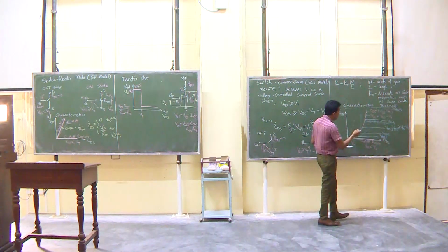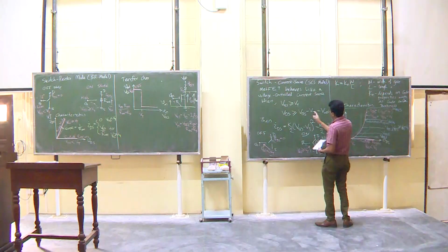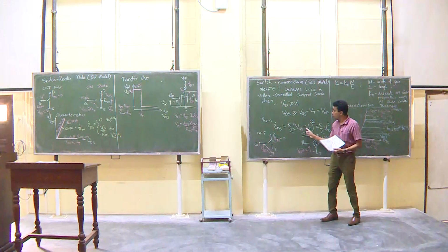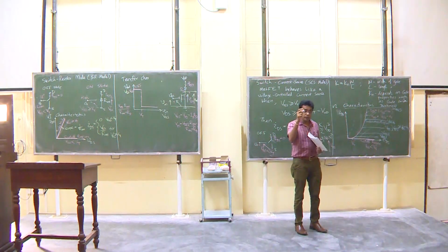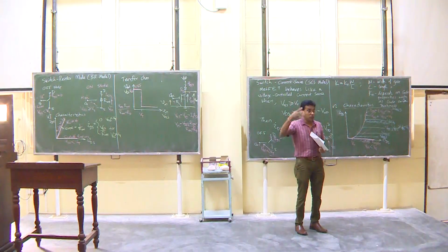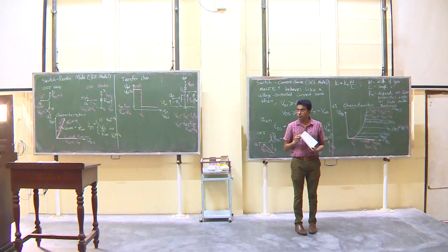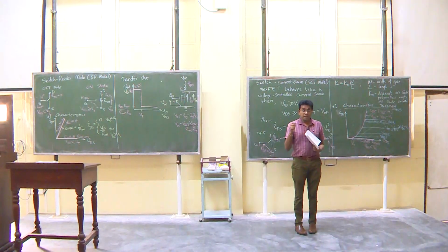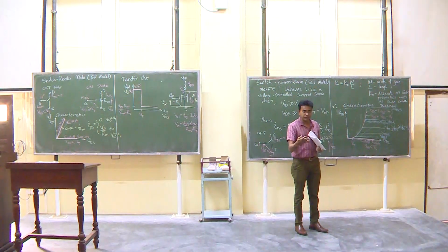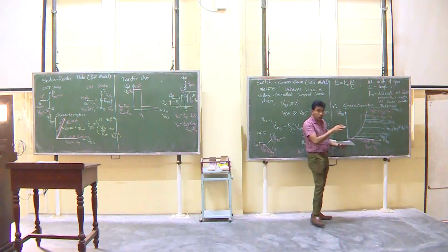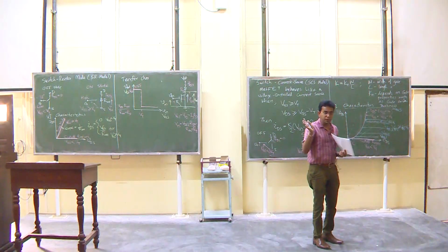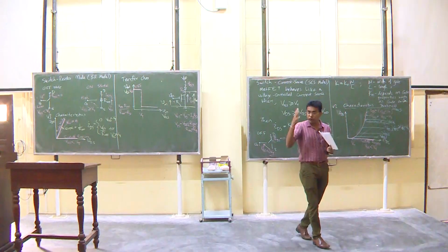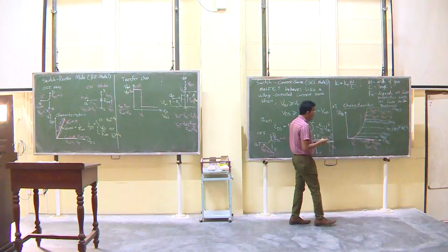This is the area where you have this relationship between the output current and the input voltage. You can control ID by using VGS. VGS is the input, ID is the output. So you can control a larger current using a small voltage, VGS. Therefore, this can be used to design amplifiers, so the saturation region is very important in designing amplifiers. Obviously, it is not a linear amplifier because the relationship is nonlinear, it's a quadratic equation, but nevertheless you can use this.